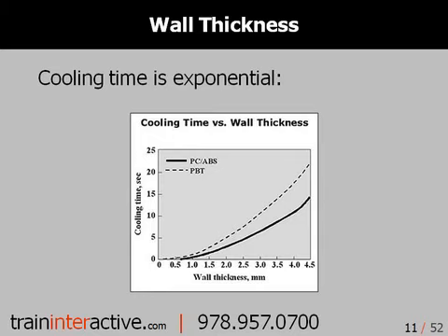Also keep in the back of your mind that both of these materials melt differently. For example, the polycarbonate ABS blend tends to soften as it melts, whereas the PBT type polyester has a very narrow melting range. These curves are characteristic of the cooling that you'll observe.